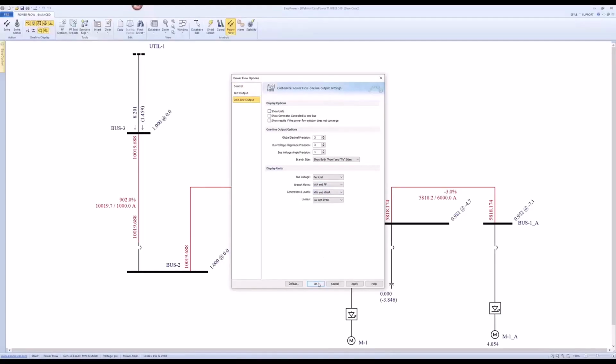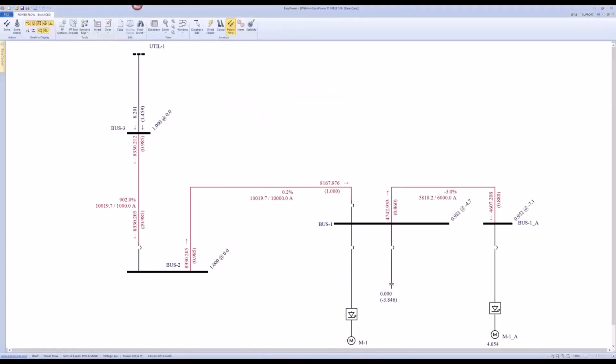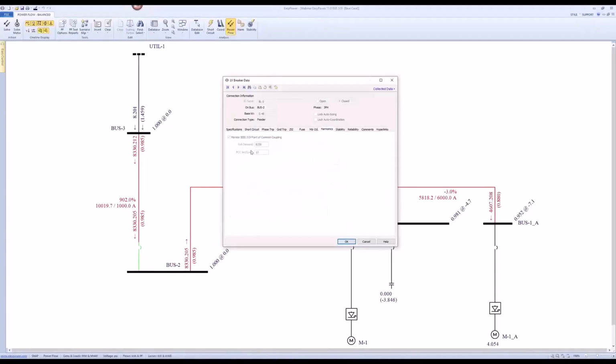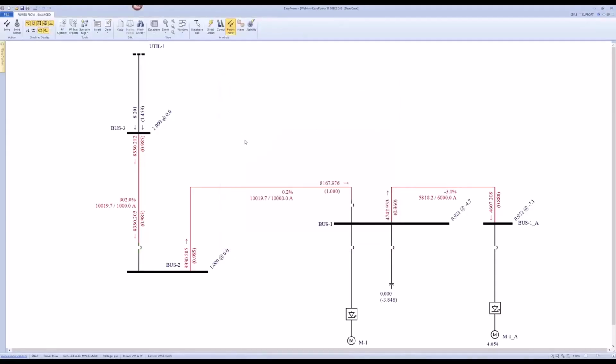So for my example, I just choose to display the kVA and power factor. My total kVA is 8330 kVA. That is why I entered my harmonic kVA demand at 8330, to tell the program what is the fundamental current to be used when I calculate my current distortion, right? Those are the quantities we needed. Now we're done with modeling the harmonic current injection. We're done with modeling the PCC with the specification about how to calculate the current and also the limits, right?